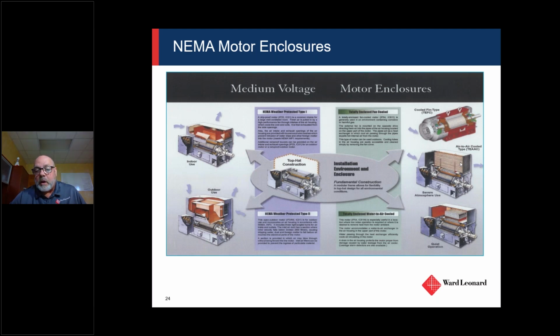And there's also a water-cooled application, and if you're using chilled water supplies, you probably have these in your plant, which is a tube bundle that has more than likely some kind of glycol solution running through it, and the motor will have fans that blow up and through and down, so it's like a circulating coolant.